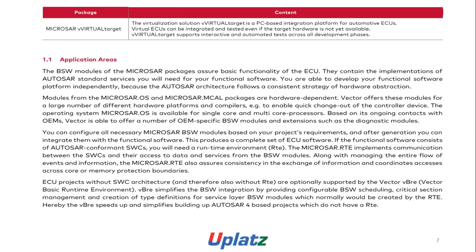If the functional software consists of AUTOSAR components, SWCs, you will need a runtime environment. The Microsar RTE implements communication between the SWCs and their access to data and services from the BSW modules. Along with managing the data flow, events, and information, the Microsar RTE also assures consistency in the exchange of information and governs accesses across core or memory protection boundaries.